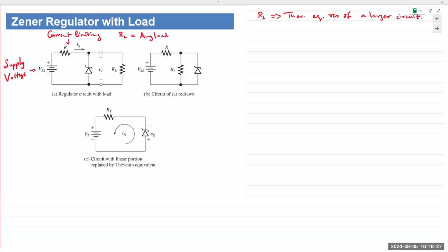Sometimes that might be easy, sometimes it might be difficult. But you would have to be aware of what that system is, what it is doing, and how the circuit is actually working. Any kind of electronic or electric machine will have some sort of power supply system at the front end. Anytime a system goes completely dead, 90% of the time, it's in the power supply line. So even if a small Zener diode like this blows out, the rest of the system is rendered redundant.